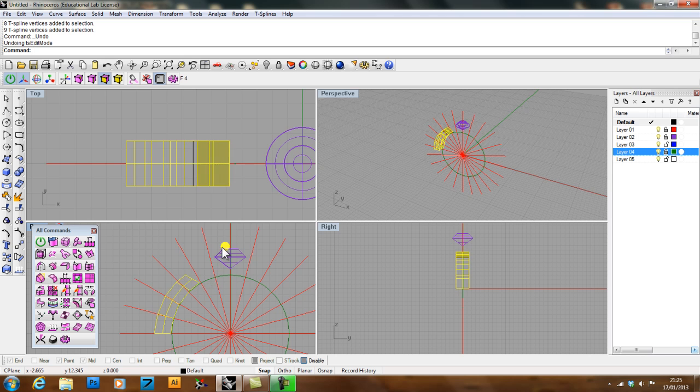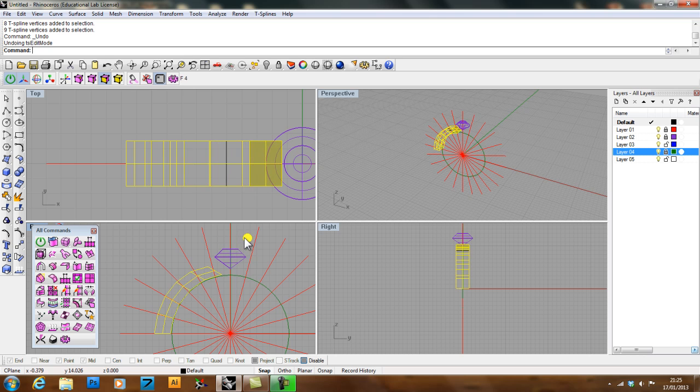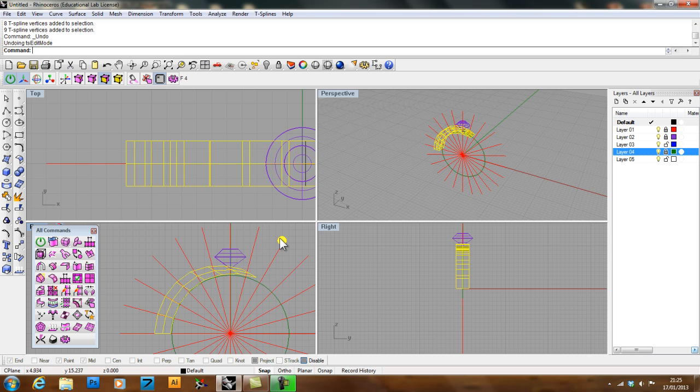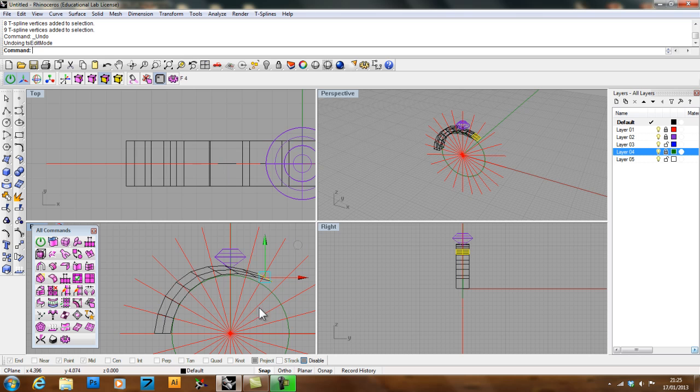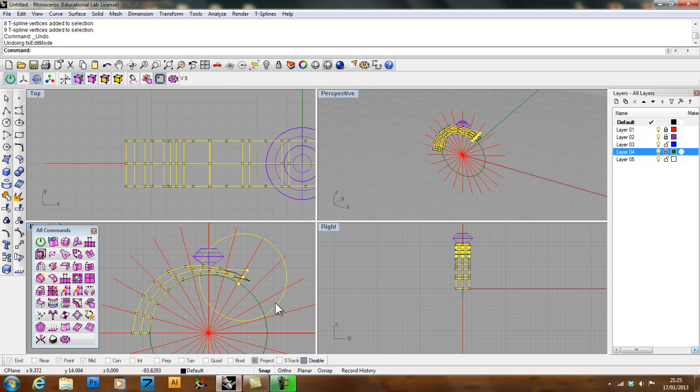So I'll do that a couple more times to get my shape all the way up to the top here, until it starts to become rather awkward to control. I'm actually going to overshoot the mark as well by 2 more shapes. As we start going around, it gets nearly impossible to control. I'm not so fussed about that because now I'm going to switch to the vertice grips and also the rotate command. And so I'm now going to rotate and position these.